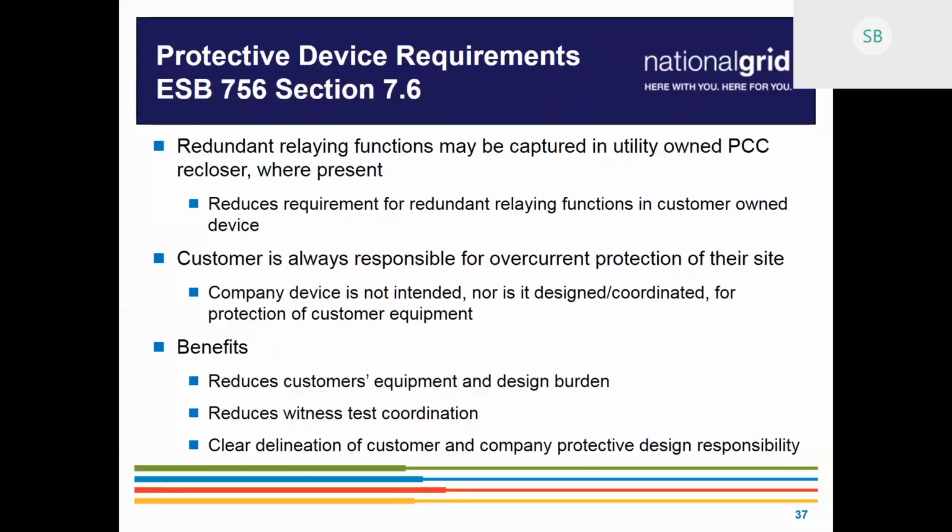So you might be able to use fuses now, whereas in the past you used the relay. So it's a design consideration. It could save some costs. And it will definitely save time on the witness test, because whereas before we had to check your settings, evaluate them, get all the tabletop review done, and then actually see it in the field and witness it, that can more or less go away. From your perspective, we would incorporate that into the commissioning of our own recloser.